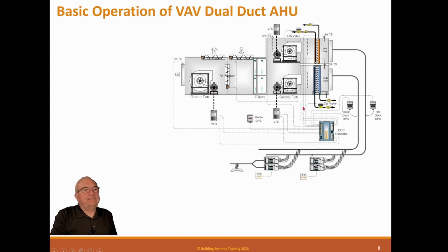Now here we show, and on the other one also, I had a return air temperature here and supply air temperature sensors here. And remember, these are dry bulb sensors, so these economizers I'm showing you are dry bulb economizers. You can use enthalpy economizers where we have a regular temperature sensor and a humidity sensor. And we normally have humidity on supply ducts also. And then we have outside air enthalpy. We can run it on enthalpy instead of sensible heat.